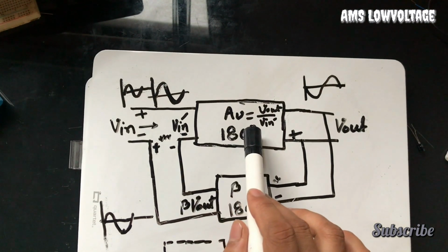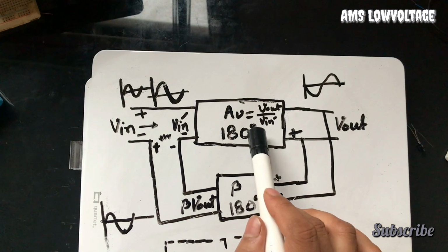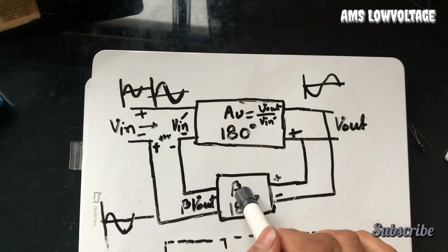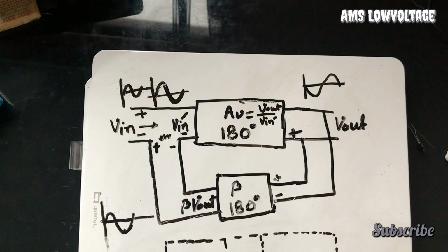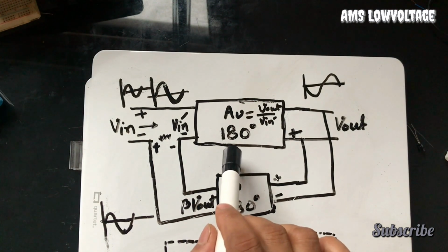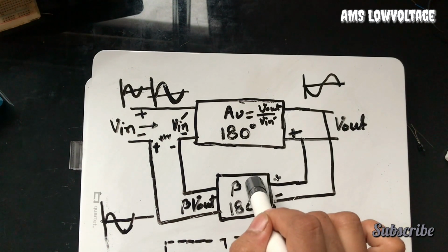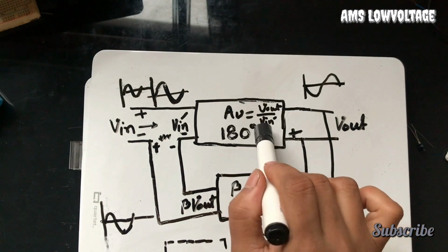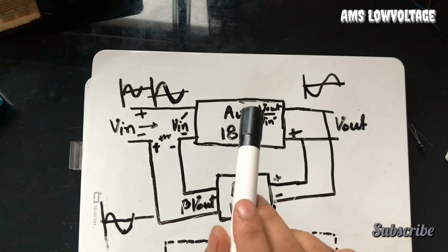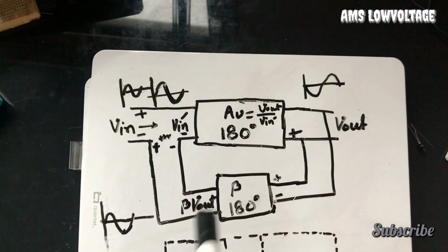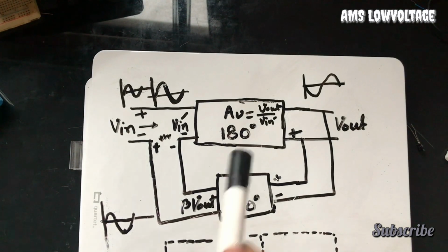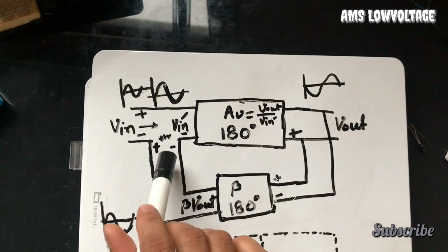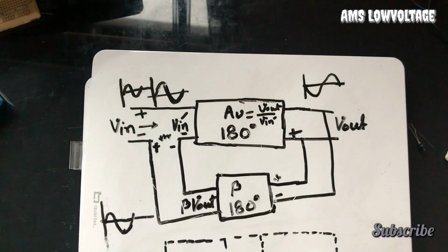So that's why this amplifier circuit must have a gain of more than 29, or at least 29, to recover the signal losses of this positive feedback loop circuit. So now we can state the condition for oscillation: we have to get one 180 degree positive feedback loop circuit from the amplifier, and this amplifier has to have a gain of at least 29 volt per volt or more. So that's two conditions, and the feedback must be positive, not negative, otherwise that will kill the input signals.